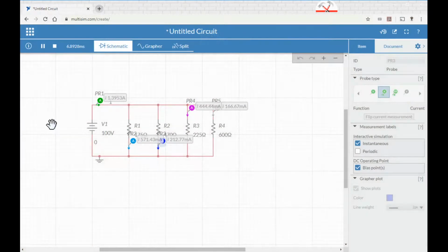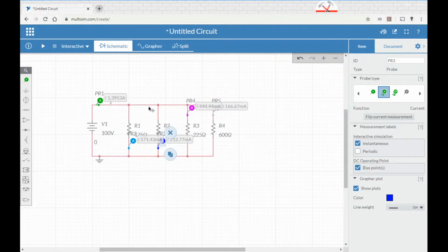you can see it gives you the same current, because the branch current here, this current right here on this side of the node is the same as this. Before you get to the junction on each end, it doesn't matter if you're in front of or behind the resistor, it's the same branch current, okay? Now, let me throw a caveat in there and talk about, because we haven't really addressed this part of it yet, but if I were to put an ammeter in, let's see here.